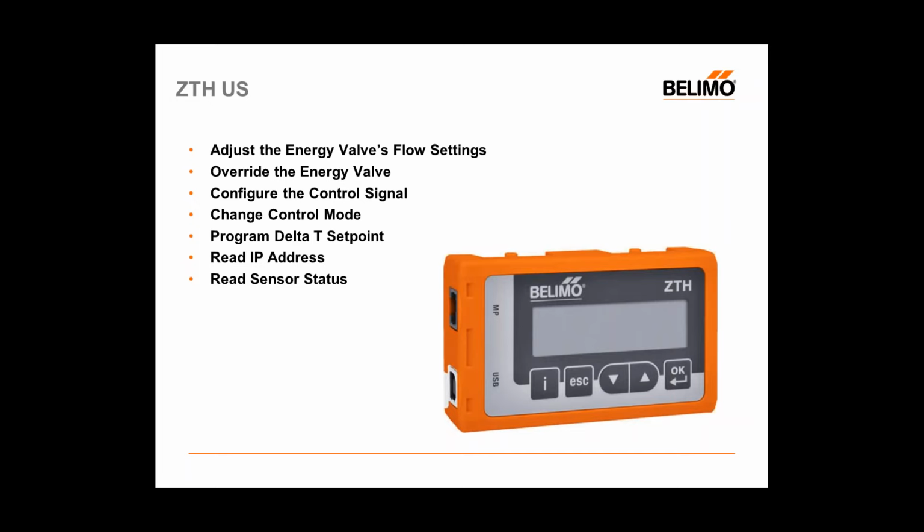If you need to go in and either configure or change the control signal or the control mode, those things can be done. You can select your delta T set point if you're using the delta T manager routine. You can check the sensor status to make sure your flow and your temp sensors are reading appropriately.